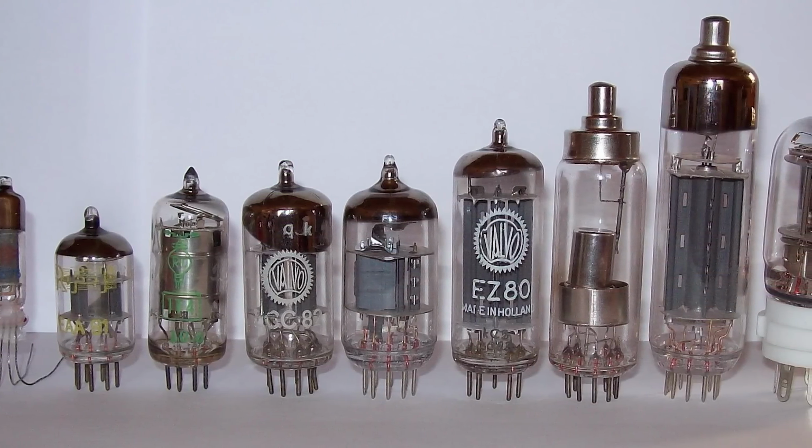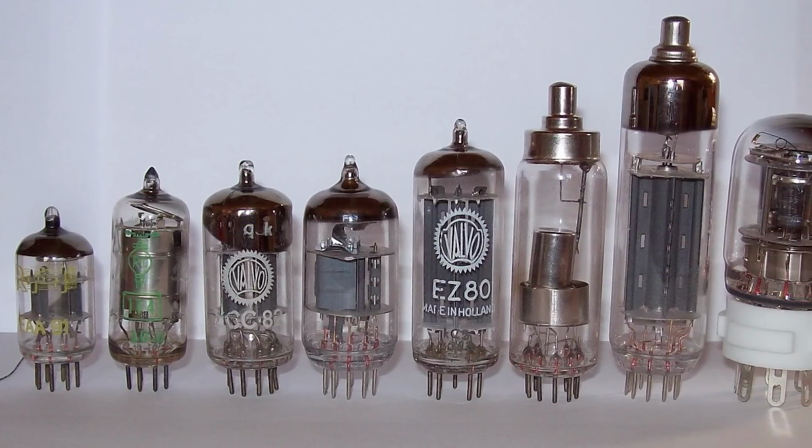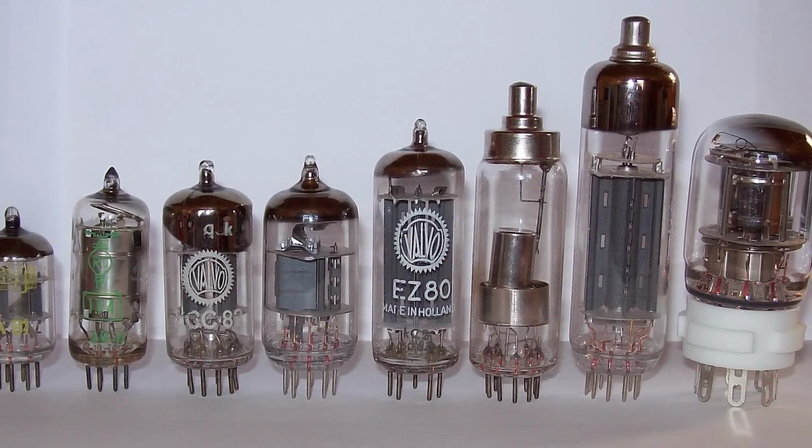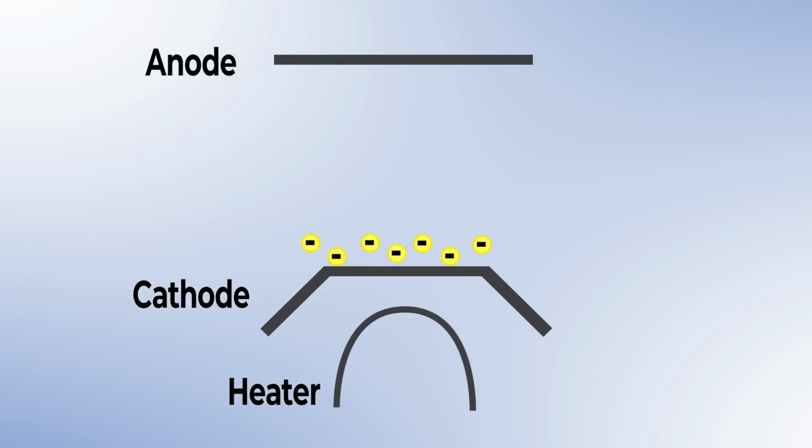In the 1950s, there were computers, but they weren't the same as the ones we have today. Computers in the 50s were all controlled by vacuum tubes. As the name implied, a vacuum tube was a glass tube that contained a vacuum on the inside that would control the flow of electricity through a heated plate. By heating an electrically charged plate, referred to as a cathode, inside of the tube, the electrons on the plate would undergo thermionic emission to the anode on the other side.